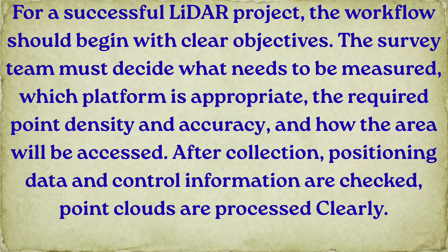For a successful LiDAR project, the workflow should begin with clear objectives. The survey team must decide what needs to be measured, which platform is appropriate, the required point density and accuracy, and how the area will be accessed. After collection, positioning data and control information are checked, and point clouds are processed clearly.